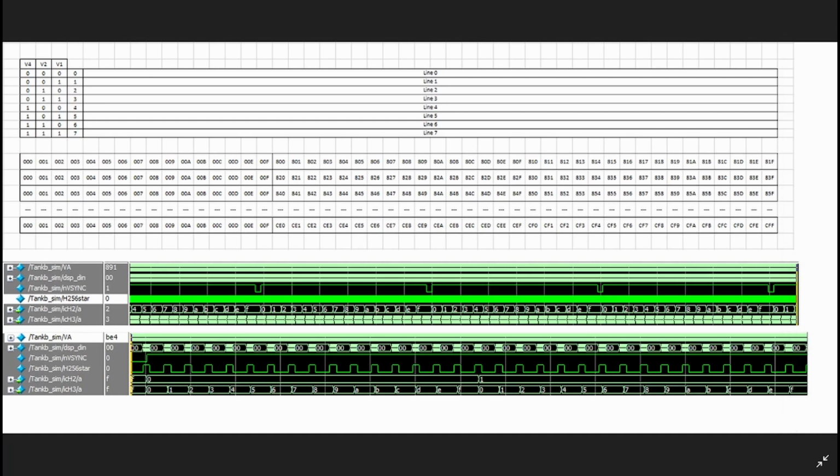Now it's important to mention that the 0 to FF is effectively each counter. So each one of these, this H blank, is a line on the screen. And then we know that one of these, a VSync, is a whole screen worth of data. So that's one screen, another screen, another screen. So what this is effectively doing is each line we get a new count. So this V count is effectively the number of lines going down the screen.